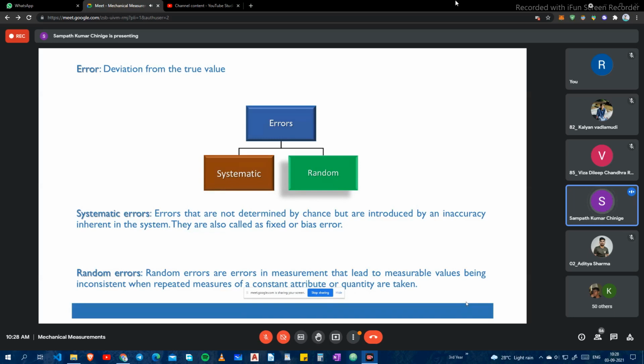For example, in the morning there is a good wind, and suddenly you are doing an experiment where you are doing flow measurement, how quickly the velocity is, and there is a flow that is backing it up. We don't know, the surrounding air is moving, and therefore some error will come. After a certain time the air has stopped and you are doing the same experiment, and you are getting a slightly lower value for the same inputs, the same standard conditions, and the same person taking the measurements.